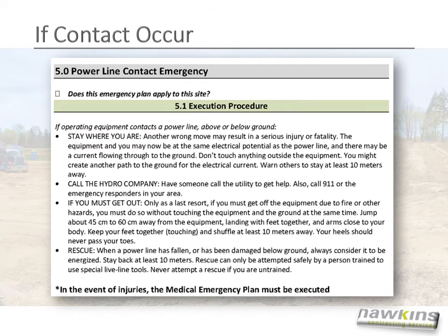And then we must perform rescue. When a power line has fallen or has been damaged below ground, always consider it to be energized. Stay back at least 10 meters. Rescue can only be attempted safely by a person trained to use special live line tools. Never attempt a rescue if you are untrained.